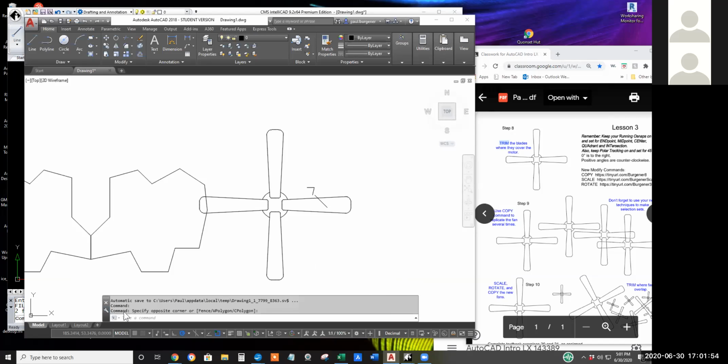But my point is, I like to have students have 3 lines of black text above the white area, because for example, in the trim command, if you only had the white area shown, you would not see this select cutting edges line. It's a little more advanced, but there are some adjustments that I don't teach. But again, 3 lines will show you all there is to see that AutoCAD shows you.